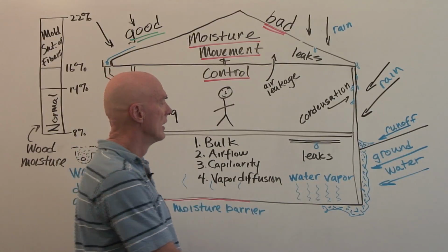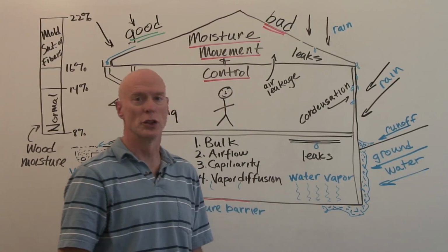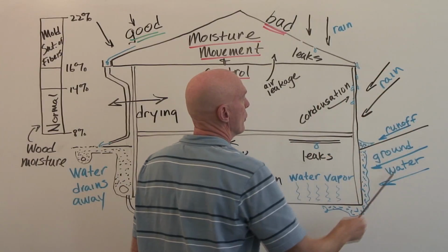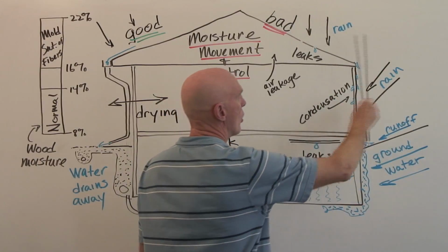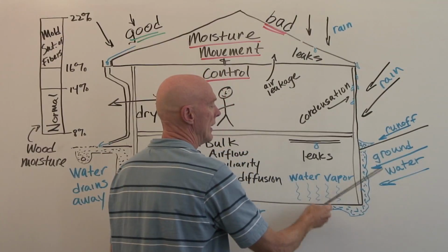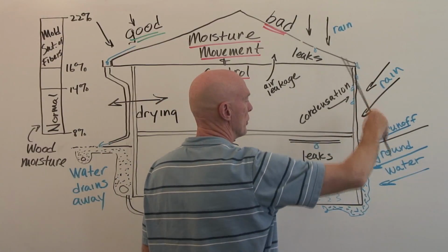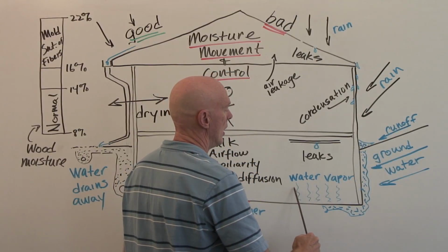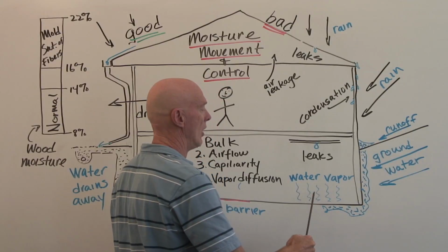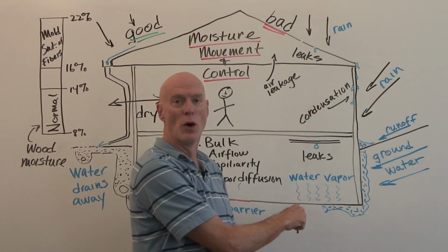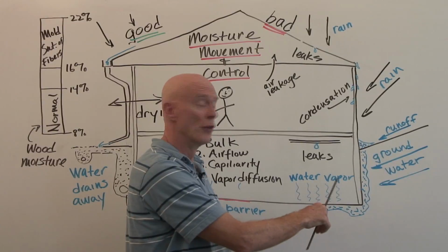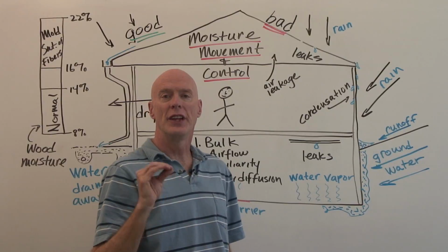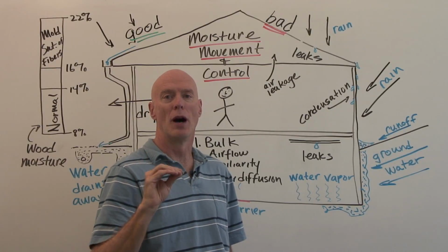These can all be related to this source of moisture, which encourages the growth of pests. Now, this flow of rain, runoff, bulk moisture entering into the building, either from roof leaks or groundwater or capillary action or water vapor diffusion from the ground, or water turning to water vapor at the surface of the floor right here and raising the relative humidity inside the home. These are the most severe problems that you'll find.